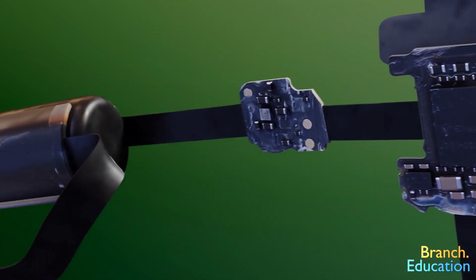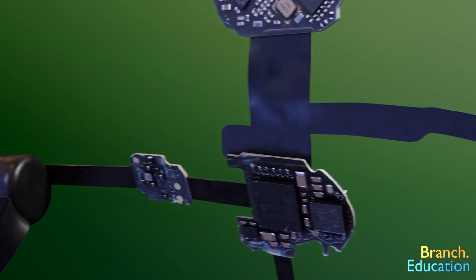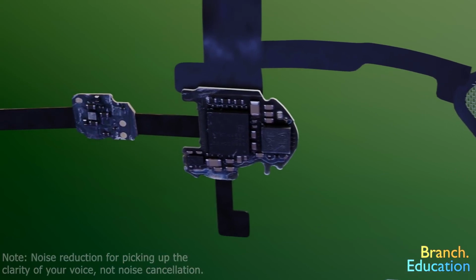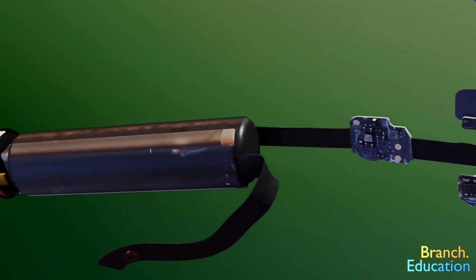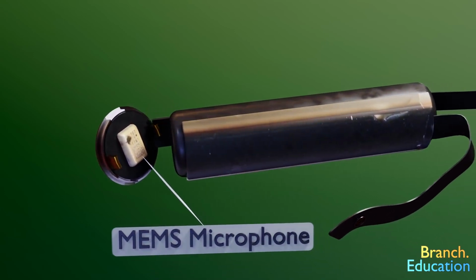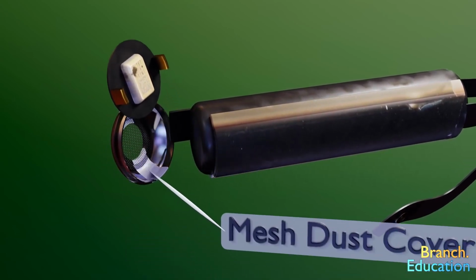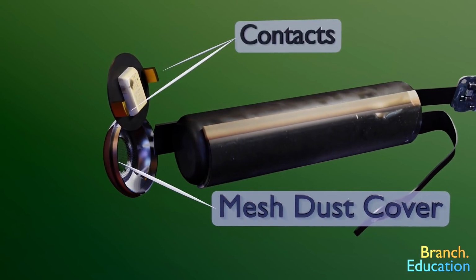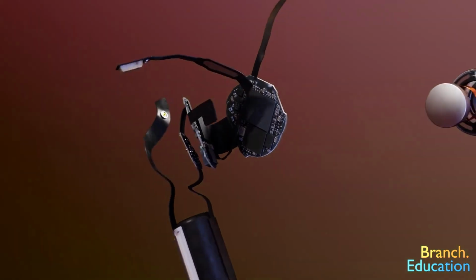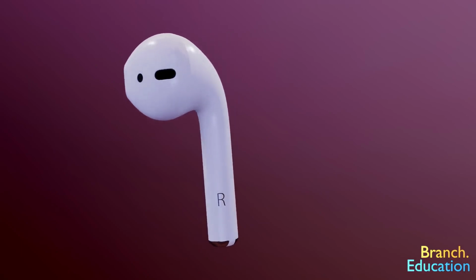Also connected to the circuitry is a flat cable for the antenna, which lies adjacent to the battery, a microphone situated at the back of the earbud which is used for noise reduction, and a third circuit board which is connected to the battery. Down below the battery is an additional small circuit board that holds the main MEMS microphone, which is about the size of a grain of rice, and below that is a mesh dust cover, along with the contacts for charging the earbuds. It's truly an impressive amount of engineering that goes into making these earbuds so lightweight and so incredibly small.